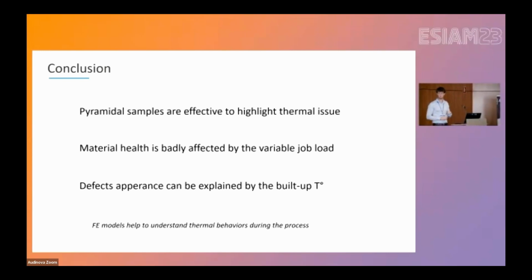Okay, I have one question. You studied the roughness and the internal porosity. Did you manage to check if there is any variation in the residual stresses in these two cases? Not yet, but there is a variation in the microstructure as well, because the cooling time changed between the steps. But for the internal stress, not yet, yeah.